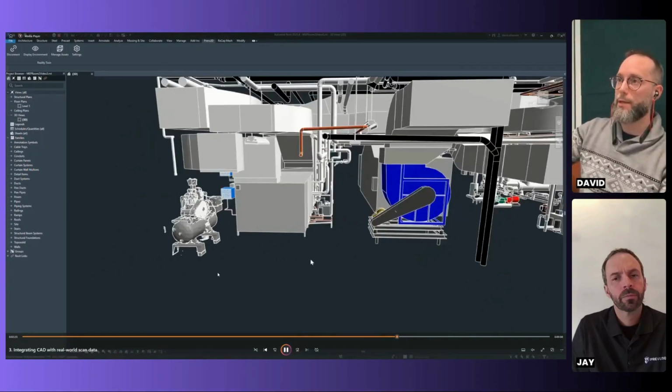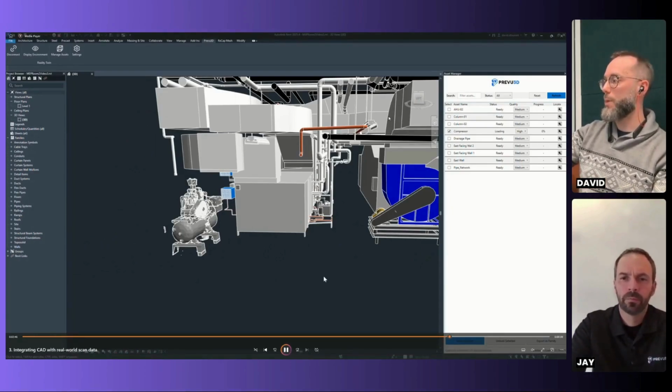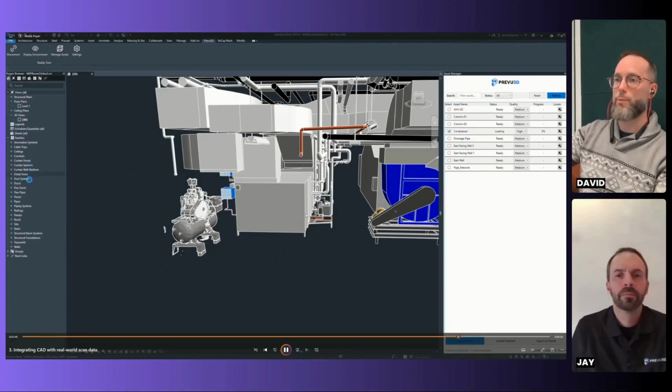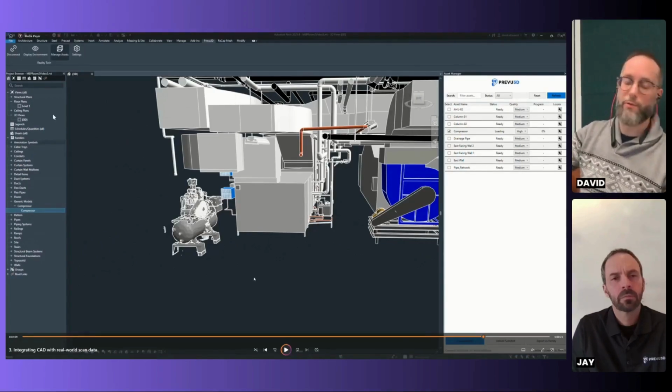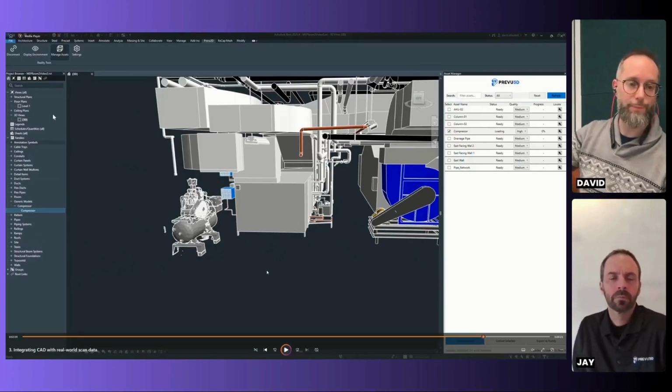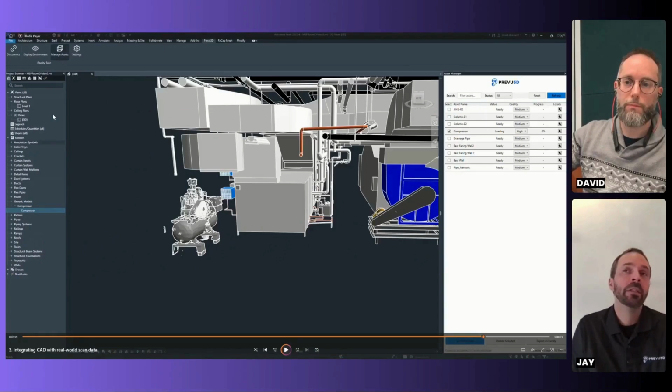So yeah, absolutely. Another option that you have inside of RealityConnect 26.1 is the ability to bring the asset as a Revit family. So this is what I'm going to show next. There's a button at the bottom of the asset manager to export as a family, and you will see it come into the generic models. So once it's in there, you can reuse it elsewhere. You can also add different properties, just like you would do any other Revit family. And that metadata can then be transposed back into RealityPlan with the 25.11 connector.